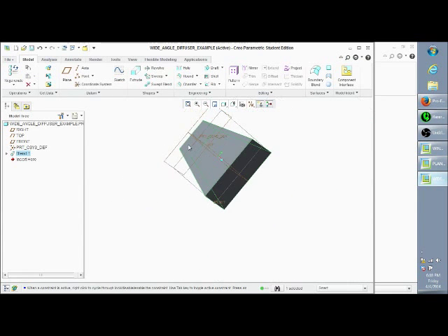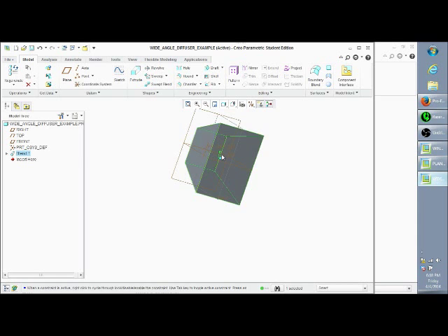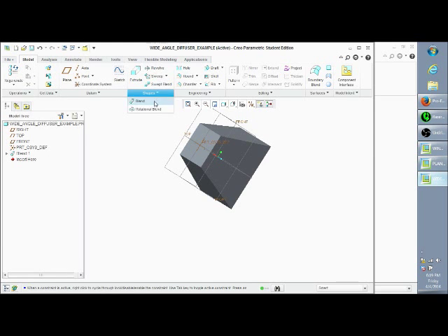Now we want to go in and create a cut through the middle to create the walled surface, because when you make your wind tunnel, you're making it out of a 0.75 inch, like a 3/4 inch, sheet of foam. So we want to create those walled surfaces. If you model it like this, it's easy to get the dimensions on the inside that you want. So go back to the Model tab, hit the down button in the Shapes tool, and then select Blend.